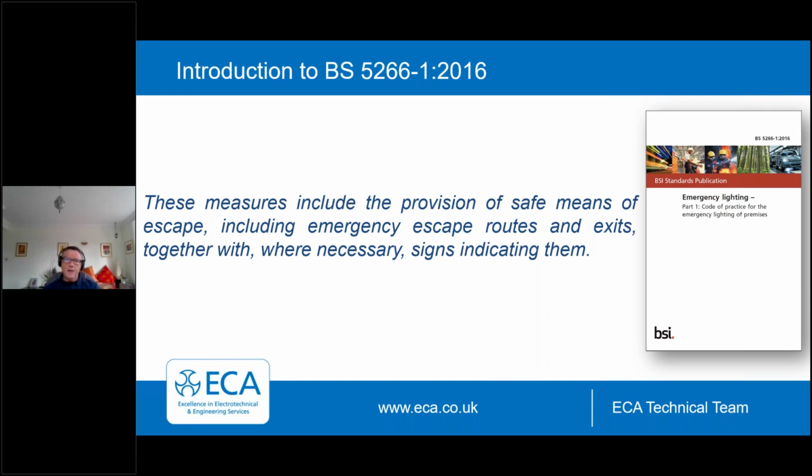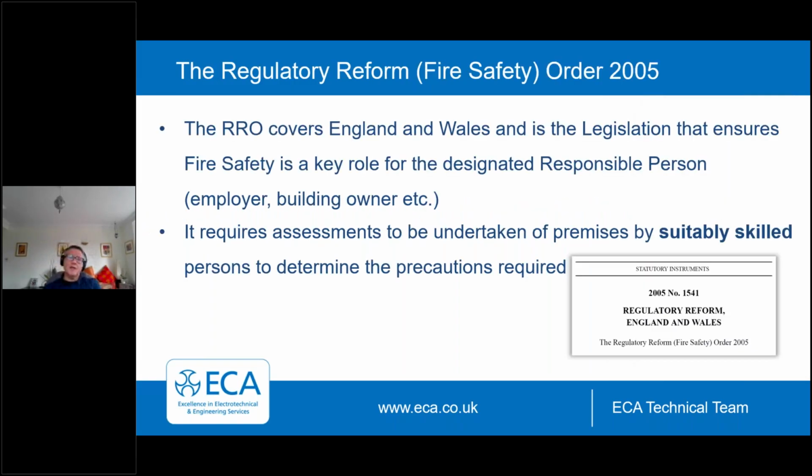This is a code of practice, but there is legislation. The first one that I'm going to refer to is the Regulatory Reform Order 2005 in England and Wales, which is the legislation that ensures that fire safety is designated as a key role of responsibility for responsible persons. As part of that, it requires an assessment to be undertaken at the premises by a suitably skilled person to determine the precautions. Now, I've highlighted suitably skilled there for a reason.